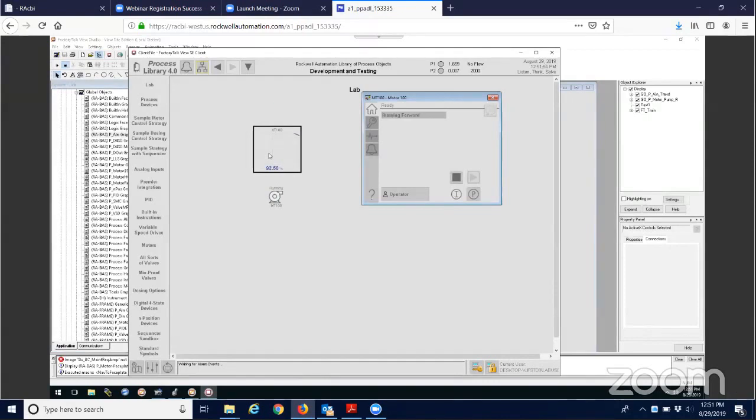So a couple of things. Again, we didn't have to spend a lot of time here developing. All these are standard, and this is 4.5, but 4.5 and 4.6 are the same interface. Notice everything's gray. We've got grays and whites, and that's on purpose. That's the ISA 101 standard. We'll get into some more of the configuration, but basically you've got this configured.